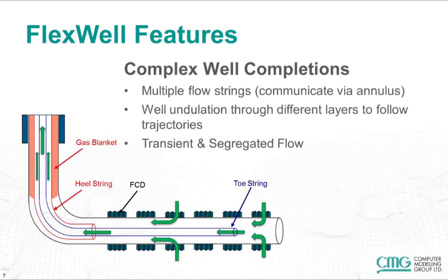FlexWell is developed to handle complex well trajectories and completions. It can handle real trajectories. So now we are able to understand how the trajectory affects the flow profile. An example would be liquid loading or fluid segregation. We can handle transient and segregated flow, and so we can model circulation and startup stages.